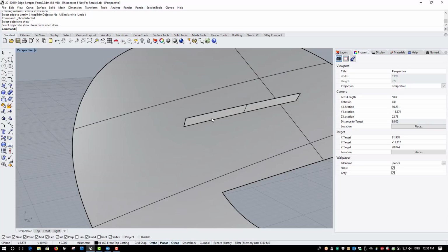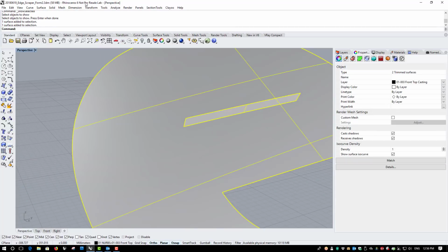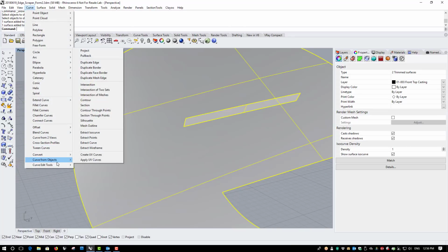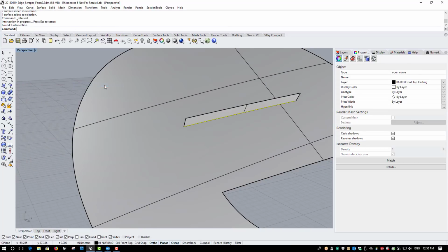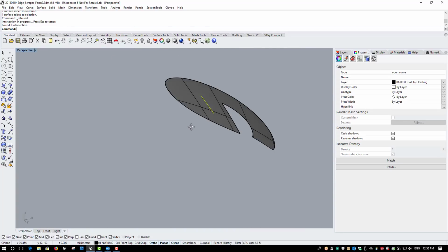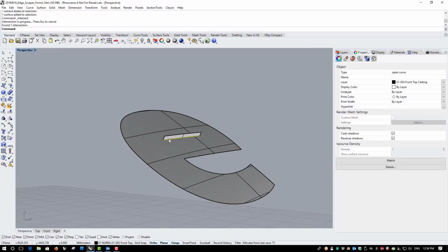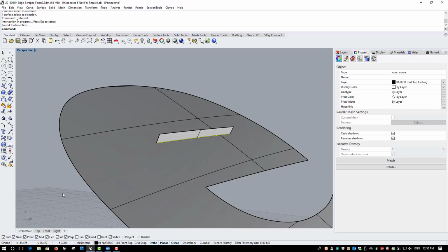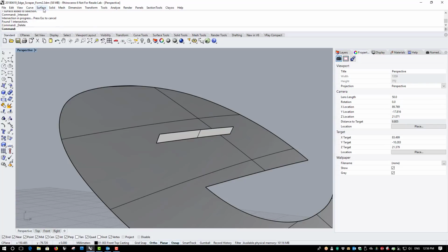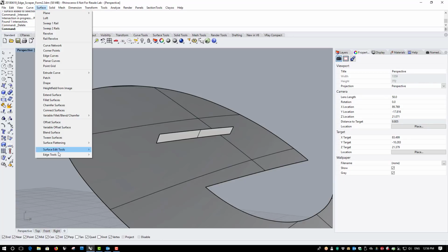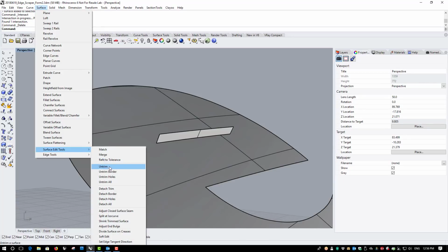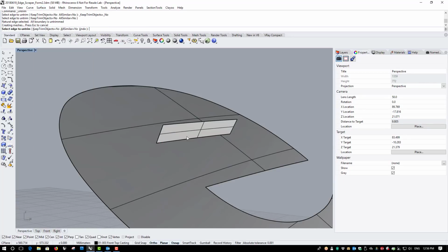and we can check whether these two parts intersect by going to Curve, Curve from Objects, Intersection. If we don't see an intersection curve here, or we see that that surface is sticking through the back of this surface, then the suggestion would be to do something like this. We would extend or untrim this surface,